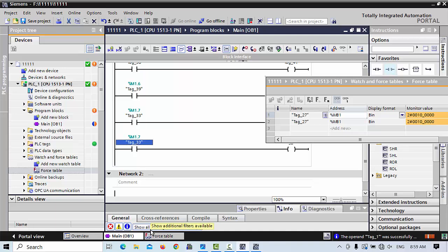That's next. See, when I write it here M1.8, it will not stop, because it says that 1 point data bit is not there, because in 1 byte total there are 8 bits. So that's finished, M1.7 is the last.